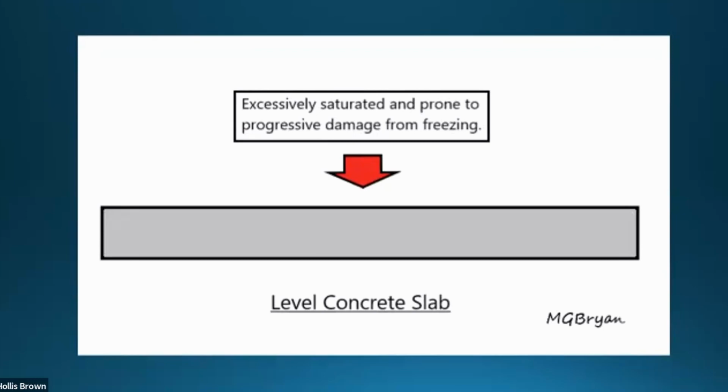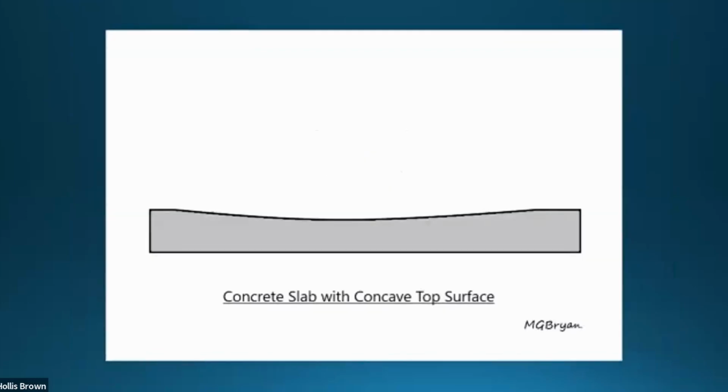When you have concrete and you pour it really flat, you don't have any slope to it, it's going to stay perpetually wet. And that's not good for concrete because the porosity is going to allow moisture to set there. And then freeze-thaw cycles will be much harder on the concrete. It's got to drain. And it's even worse if you have a convex surface where water stands. That's worse yet, because you're going to have not only saturated concrete, but then you've got slippery ice on top of it, and also your chances that the concrete is constantly being stressed by freeze-thaw cycles in all the pores of the concrete, it's going to accelerate the failure of your concrete.